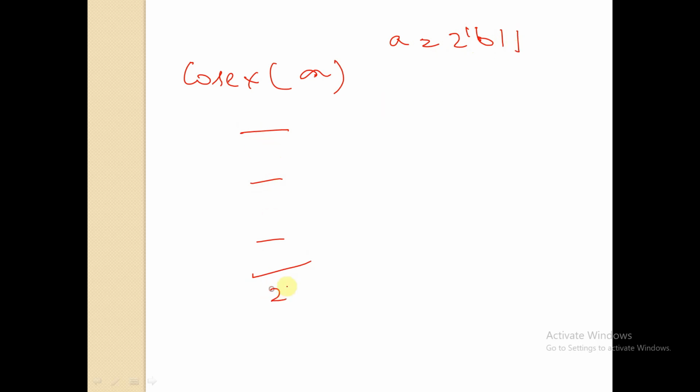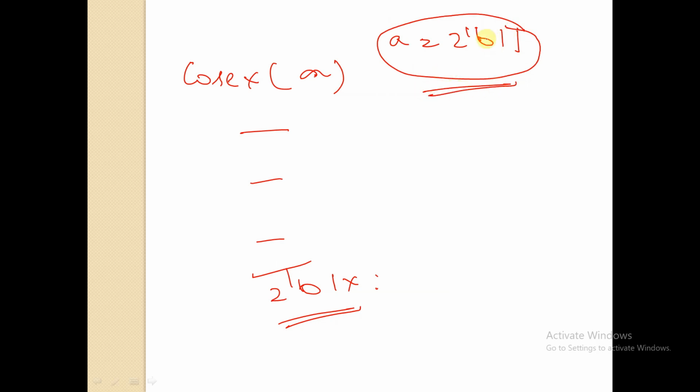So you are asking casex A, and there are some statements here. If A is equal to 2'b11, and here we have a case of 2'b1x. Here we are directly giving the value of A as 2'b11, so it will search for 2'b11.